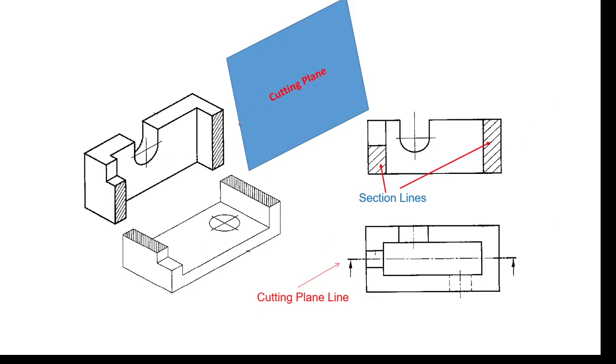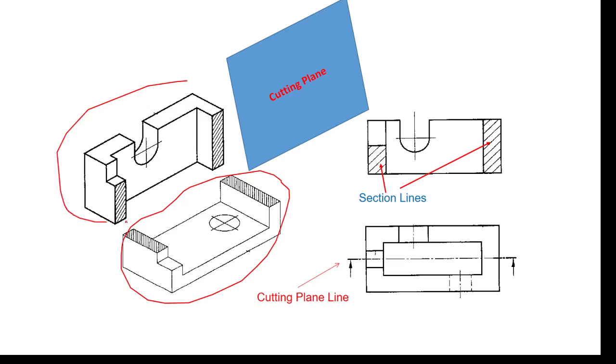Select a suitable cross section, and at the cross section, using such an imaginary knife, an imaginary plane, cut the object. After making such a splitting, remove away the obstacle. In this example, this part of the object is the obstacle, so throw it away. Imagine as if there were no such part. Observe the rest. This is the remaining part of the object after the imaginary cutting process.